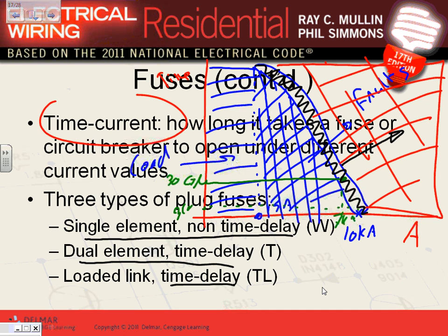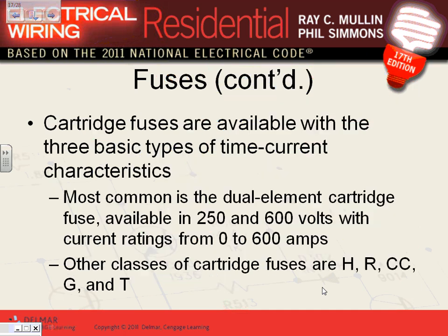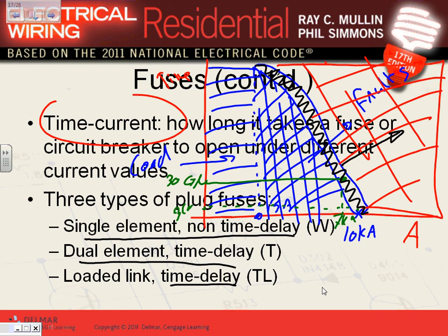If you guys get this one now, as we move into the fuses and the coordination, that will help you a lot. Any question? The most important thing is time delay and non-time delay fuse. We use them in motors. If you remember, Chris, if it's a non-time delay fuse, 300%. If it's a time delay fuse, 175%. Because we can have a smaller fuse, since it allows the motor to start. Okay, questions? Any questions?